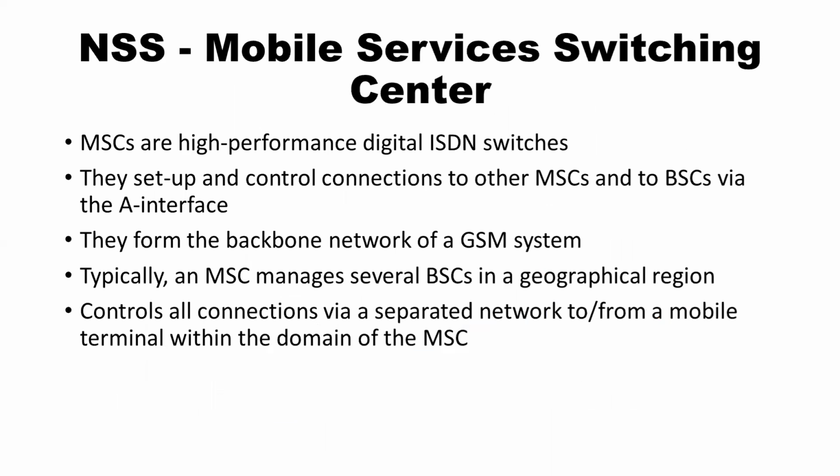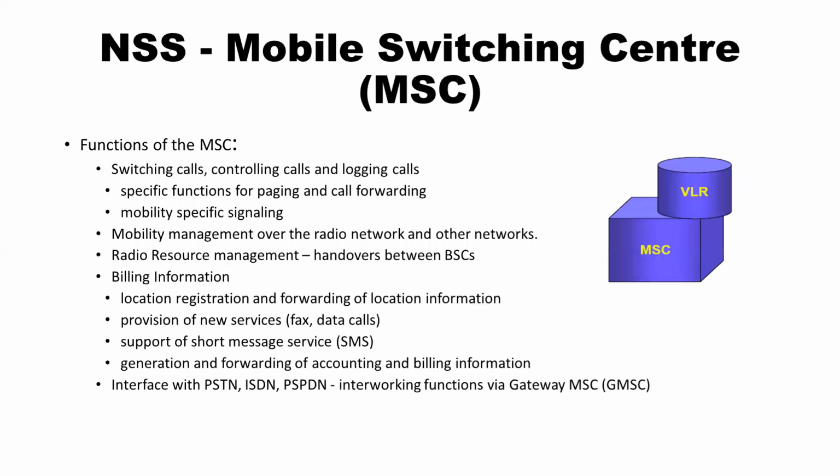Mobile Services Switching Centers, MSCs, are high-performance digital ISDN switches. They set up and control connections to other MSCs and to the BSC via the A interface. They form the backbone network of a GSM. Typically, an MSC manages several BSCs in a geographical region and controls all connections via a separated network to and from a mobile terminal within the domain of the MSC.